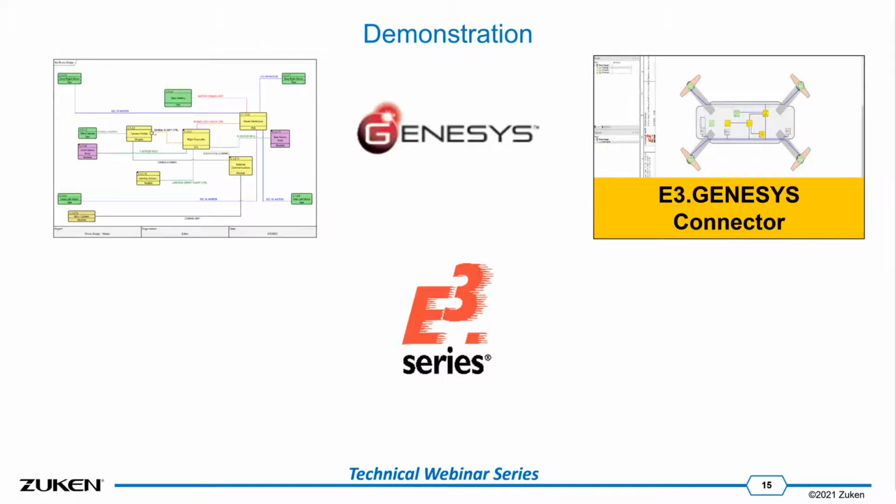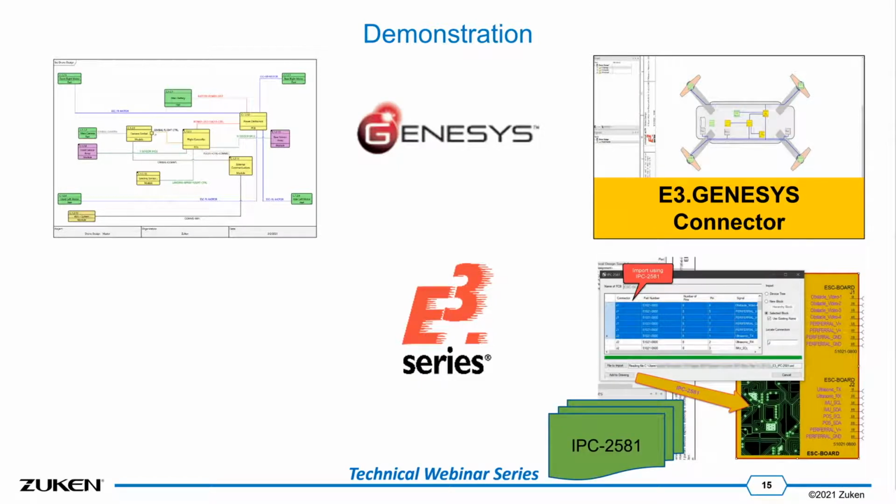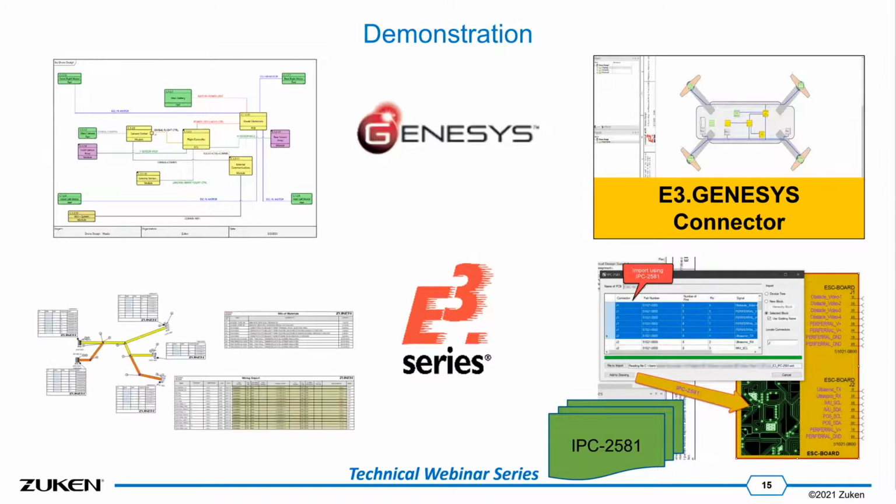We'll also talk about how we access the model, the parameters and the requirements from detailed design into GENESYS. We'll talk about the feedback that is required, as well as talk about how to create the wire harness design and use the IPC 2581 to finally drive the manufacturing drawings from detailed design. So let's get right into it.